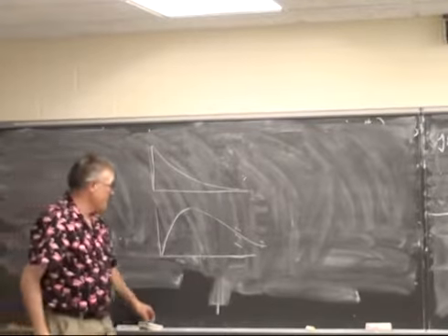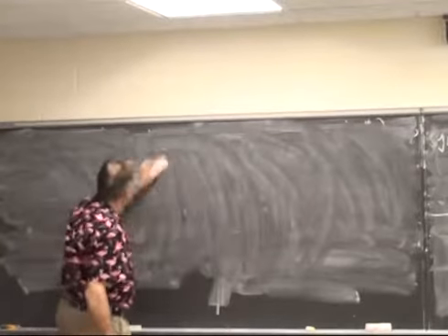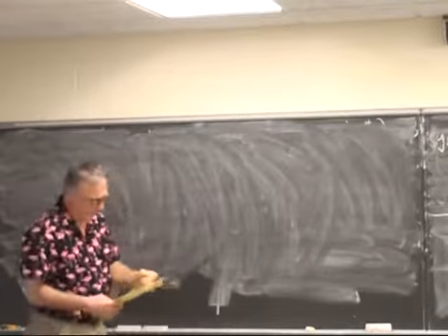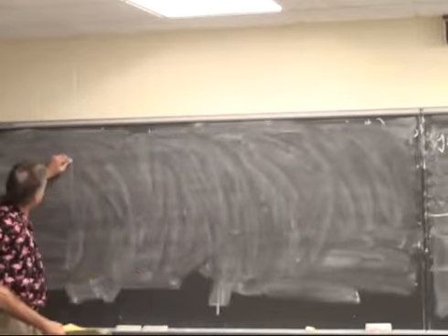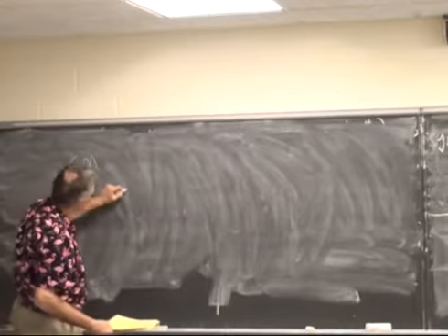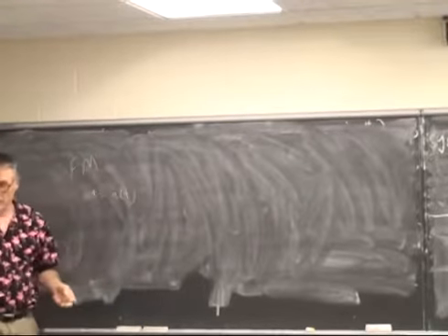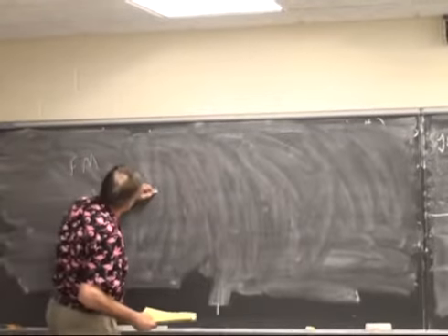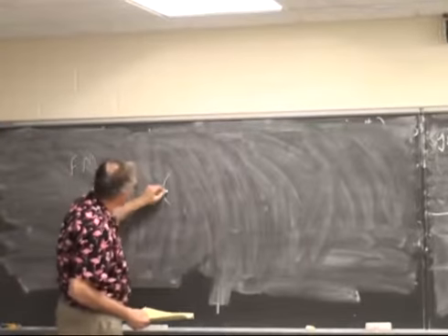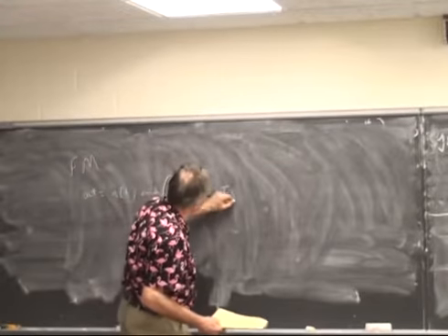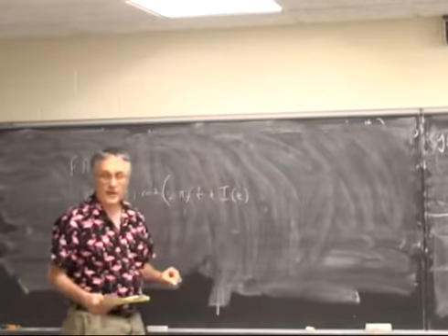FM synthesis, or so-called empirical synthesis, is quite different. There's no particular rational way of designing it. For FM synthesis, the output is going to be given by some A of t, some amplitude envelope, which again is going to be more or less exponential rise and fall, times some cosine 2 pi f t plus some other amplitude value.